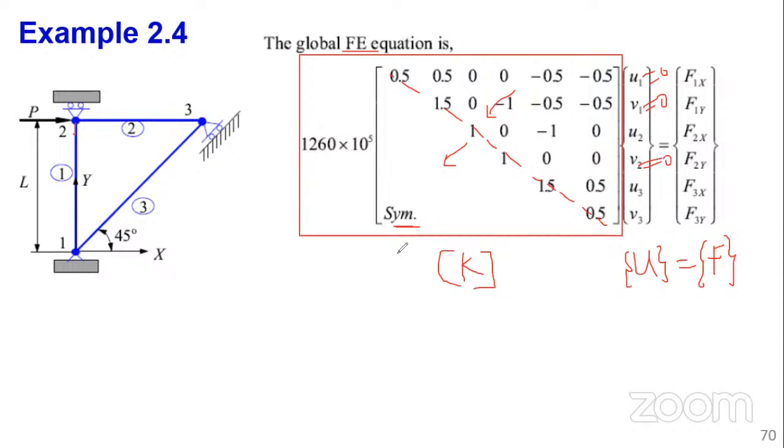What other information do we have? Because if we derive this, we'll have how many equations? 1, 2, 3. We'll have 3 unknowns. But we are given a condition here. We see this is roller support. So U3 is not equals to 0. Okay. But we know V3 is equals to 0 because of this roller. There's no movement upward, but it can move to and from.